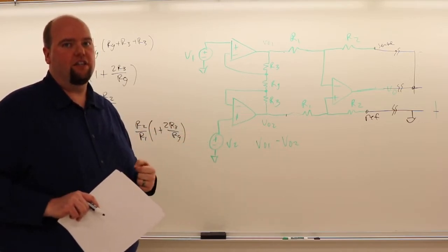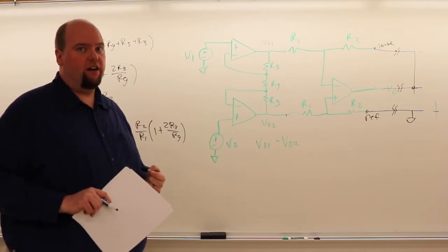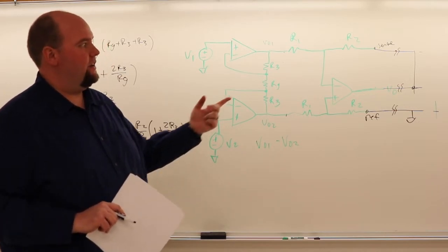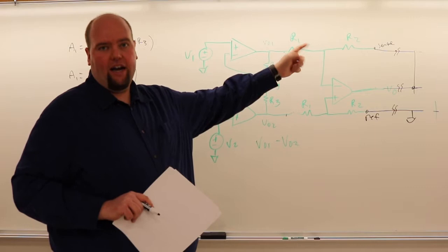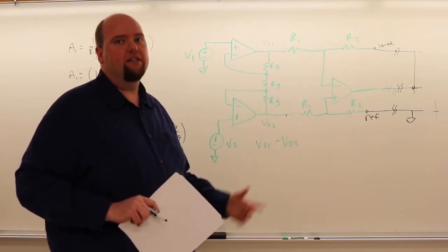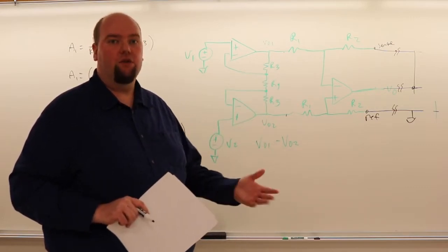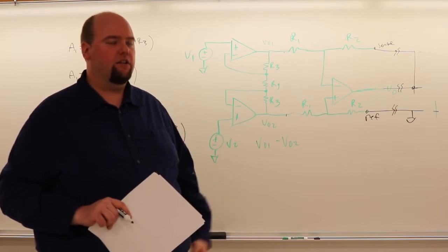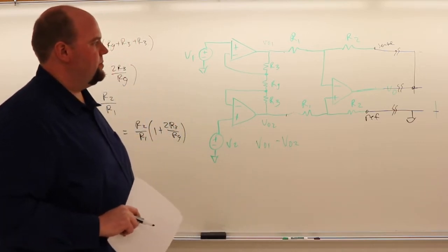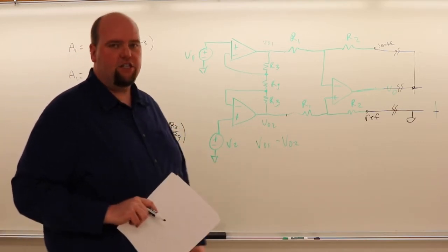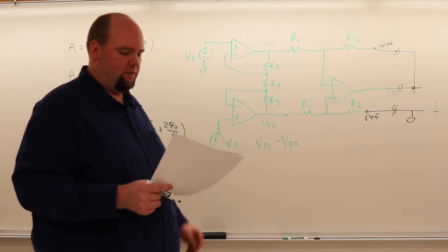And so it's really important that you look at the data sheet. Make sure you're using it correctly. Also because quite often it will require an external connection between, say, sense and the output. Even if you're not really using it for its intended purpose, it still does require that connection. So always be sure if you're working with an exotic instrumentation amplifier to check these things.